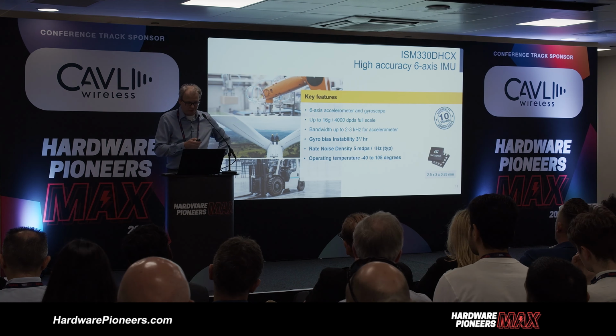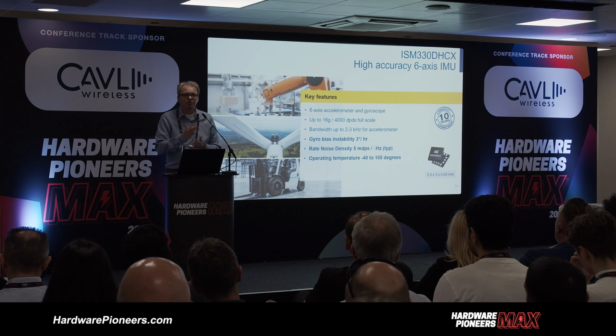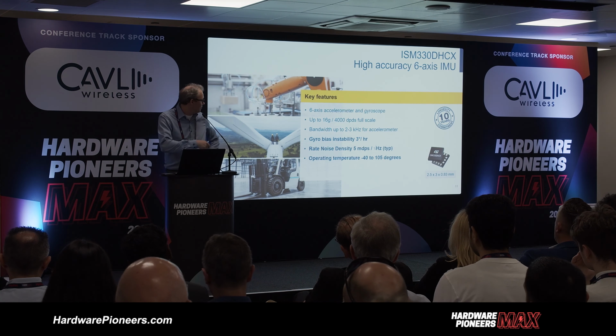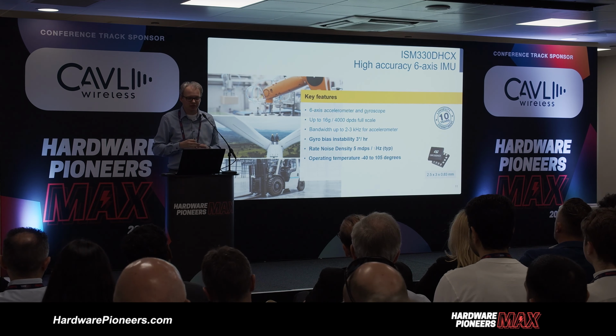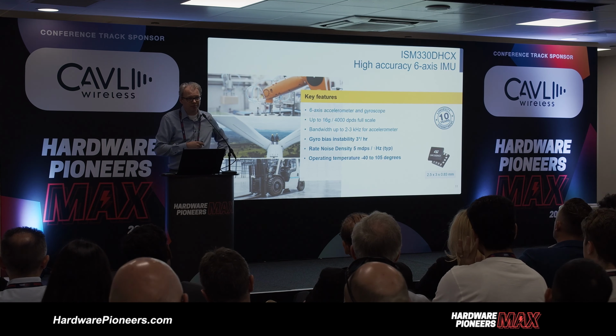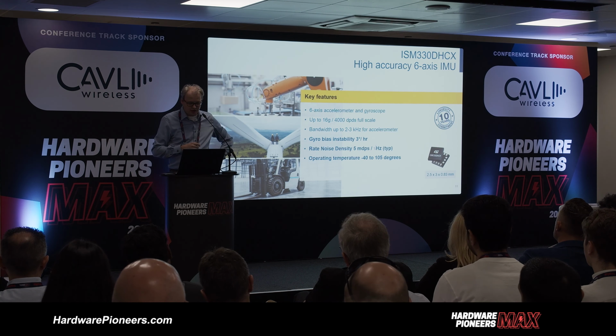The key parameter from the component perspective is this bias instability. It means that the component drifts only 3 degrees per hour, so it's a very accurate component. Also, the other key parameter is the noise density. Again, to measure very weak signals, you need very low noise in general. And one of the applications could be forklift applications, to measure how the forklift is vibrating and how people are using it when they're operating it.